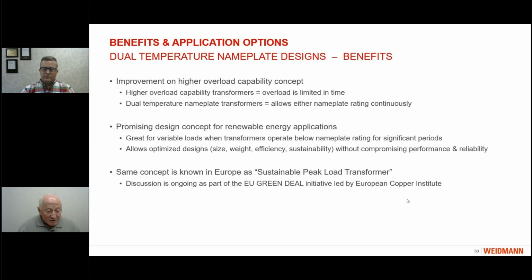And this provides a good opportunity, especially in cases where we have a very variable load, as in cases of renewable energy transformers, where load is not constant. We can design transformers that are better utilized by having these two different levels of capacity at two different temperatures. A similar system is discussed as a part of the EU Green Deal initiative, and it's called Sustainable Peak Load Transformer.